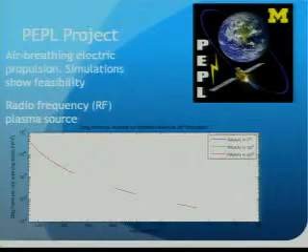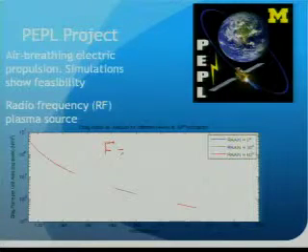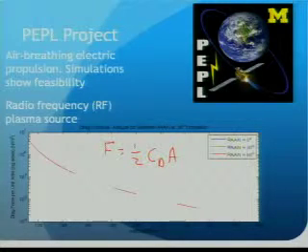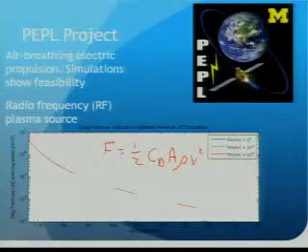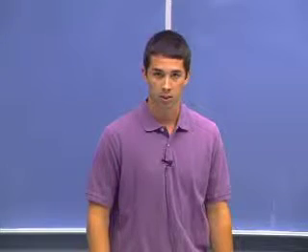the equation F equals 1/2 C_D A rho V squared, where C_D is the coefficient of drag, and that is a user-defined quantity in STK, and in our case it was 2.2. A is the incident area of the satellite, and that is also a user-defined quantity in STK, and in our case that was 1 meter squared. Rho is the atmospheric density, and that is an STK report, and V is the satellite's velocity, and that is also an STK report.